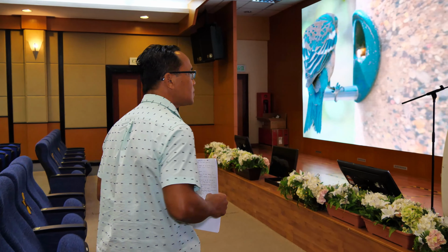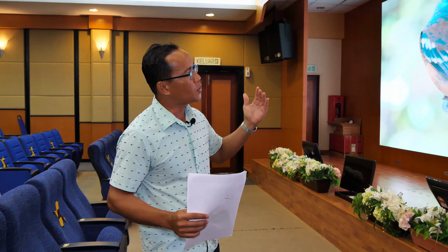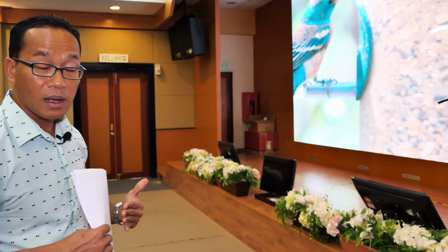The pixel is important, but that doesn't mean that pitch 4 or 5 is always better than 2.5, because you have to look at the viewing distance. If you come closer to me, here we propose we are using P2.5. Usually the rule of thumb is you just multiply by 2 to get the viewing distance. Viewing distance is where I'm standing right now, the distance between the screen and where I'm standing.